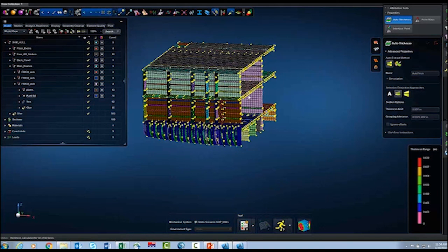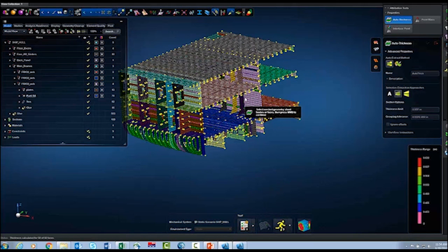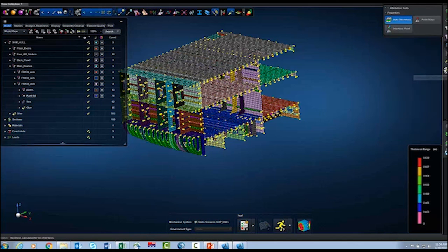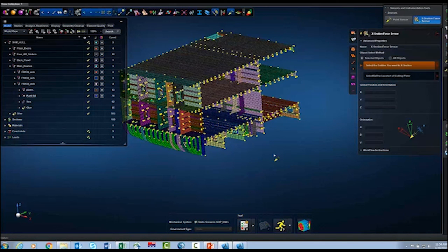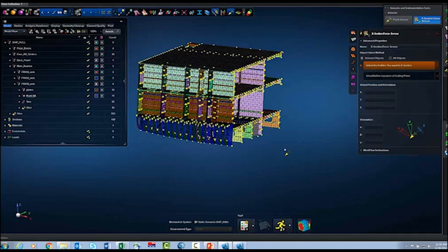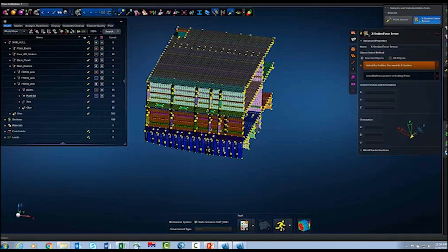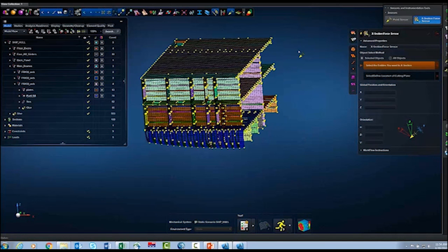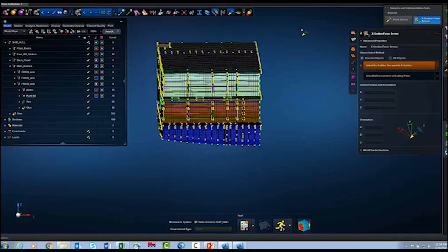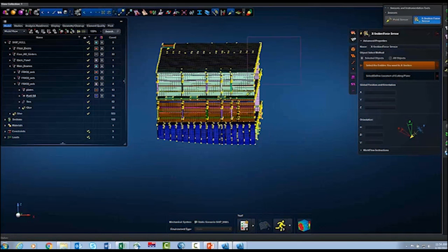Now, one thing I wanted to show, and I forgot to do as I was talking before: a lot of people like to look at the shear and the moment that's propagating in a large structure, especially if you're doing a larger loads model. In the Grizzly release, we've added these cross-section sensors, and I would simply say I want to know the moment at a location in the structure.